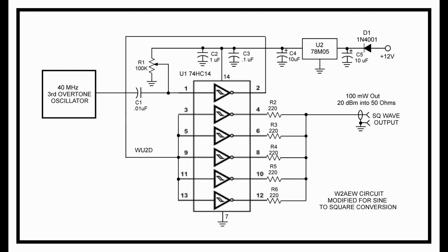Notice I have 3 capacitors on the positive pin of the chip. We're trying to bypass the chip at low, medium, and high frequencies. Don't be afraid to add even more, and make sure that you bypass pin 14 directly to ground and use a ground plane if possible.